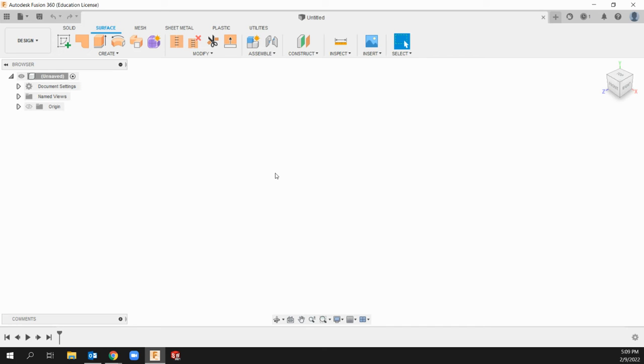This can be used for many things. If we want to mask something such as a hole or a cavity, we can do that. When you get into programming for CNC, like a milling machine, a lot of times we'll have holes and cavities and openings and pockets that we don't want the machine to cut material over. So we can apply a surface to that area, and then it gives us a boundary or geometry to avoid.